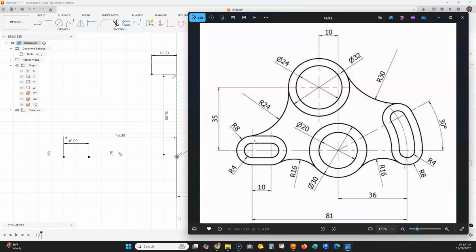So we have one other construction line to draw, and that is this arc or curve in here. This is what we'll call a construction circle or an arc, and we're going to use the circle command to do this. You might see that we don't have anything specifically telling us what the radius of this is, but we kind of do because we have the origin here and we have the distance of 36. This right here would be a perfect quadrant of a circle if we were looking at points north, south, east, west. This over here would be the east point, right at a 0 or let's say 90-degree point of a circle.